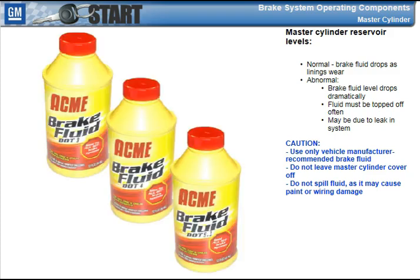During normal operation, brake linings wear down and brake fluid fills up the space created. This causes the fluid level in the master cylinder reservoir to drop slightly. If the fluid level drops dramatically or needs to be topped off often, there may be a leak in the system. There are several precautions to observe when working with brake fluids.